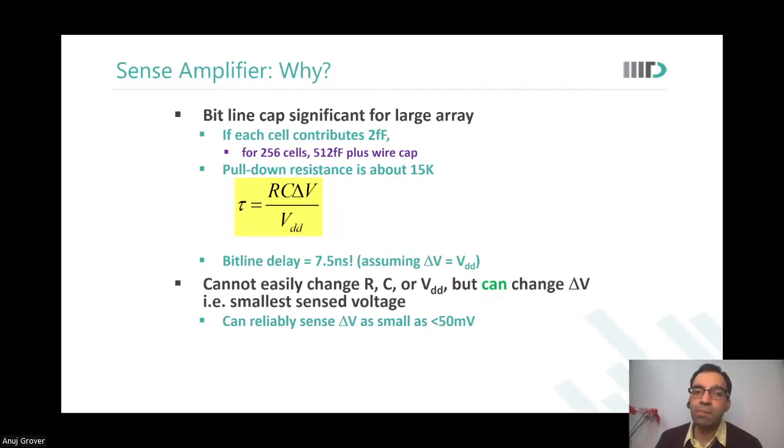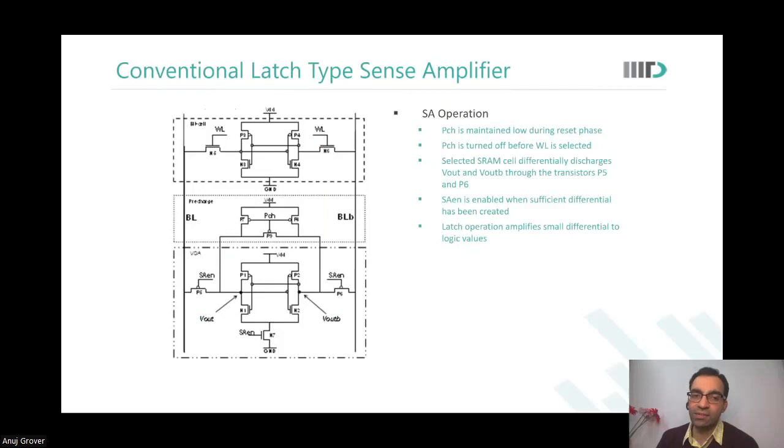So the sense amplifier is a high speed and low power solution to the speed and power trade-off. What goes for a toss is which figure of merit? Area. In terms of PPA, performance and power are both improving at the cost of area, because there are so many transistors in a sense amplifier.